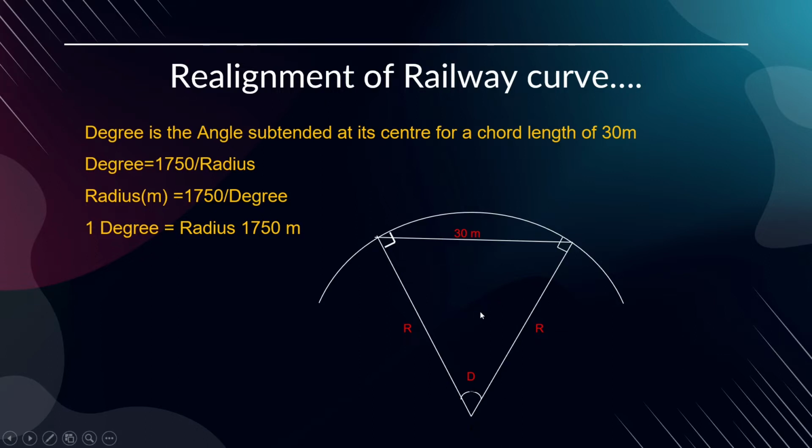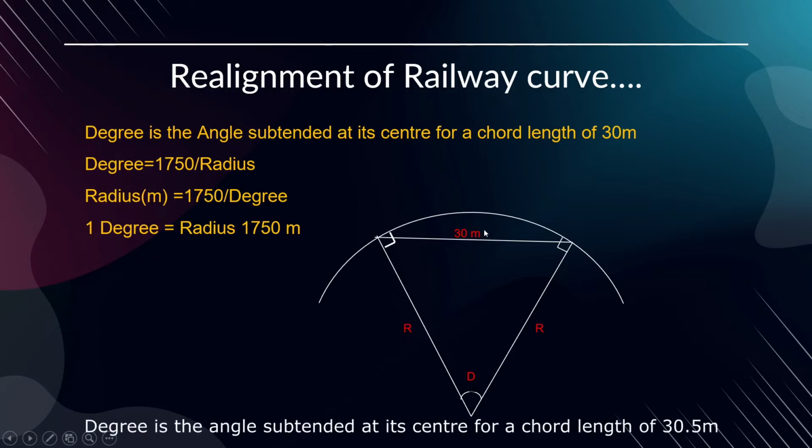It is nothing but pure trigonometry. It is for the complete circumference. We take 2 pi r, which means the angle subtended at the center will be 360 degree. Suppose it is 30 meter, because here we take arc length equal to 30 meter, since the curvature is negligible for a large radius. So we take arc length equal to chord length, almost.